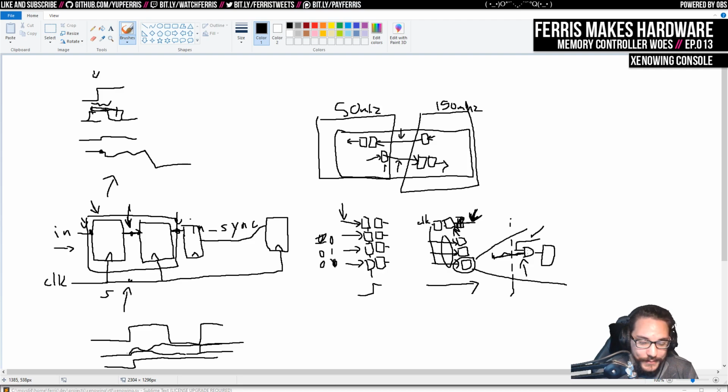So it would add some latency to your design. Essentially, anytime you're crossing a clock domain, or synchronizing any signal into another clock domain, it will add latency to your design. And you need to be very careful when you do it, because you need to make sure that stuff like this is safe.